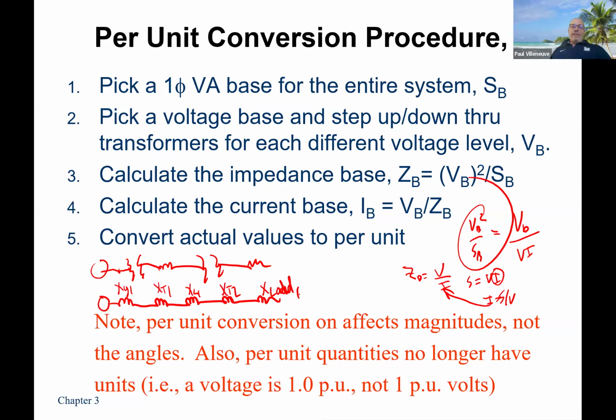Yes, sir. In your diagram, XT1, if T1 is a step down transformer... It's probably a step up transformer, yeah. That's my generator. It steps up the voltage, most likely. Now, if on the right side we have, let's say, 13 kV, that means that going downstream it's probably 13 kV all the way down. Yeah, everything down there is still 13 kV from the other side.